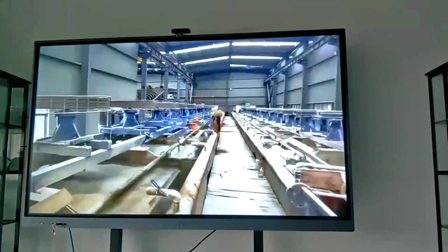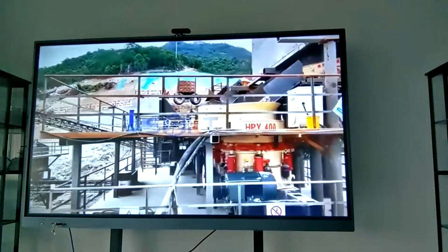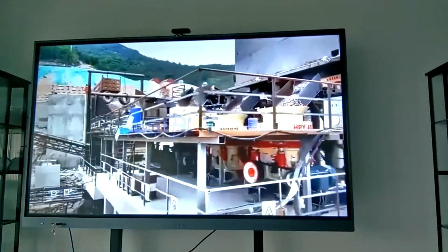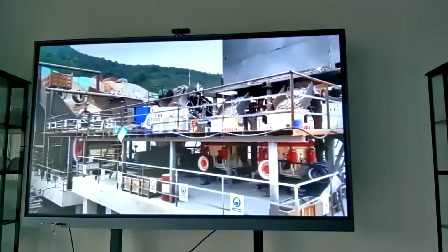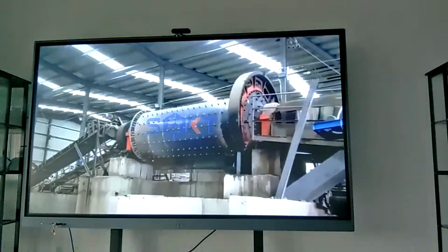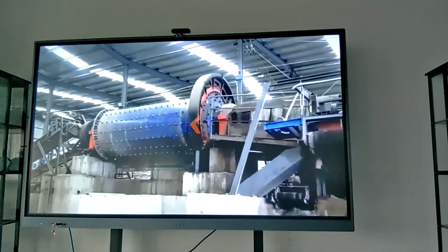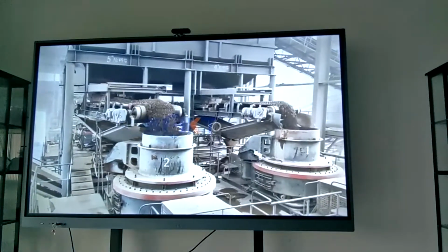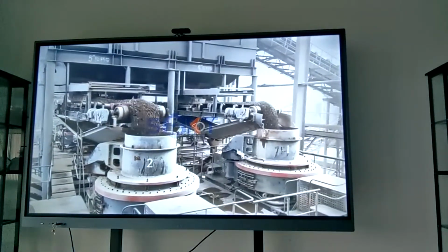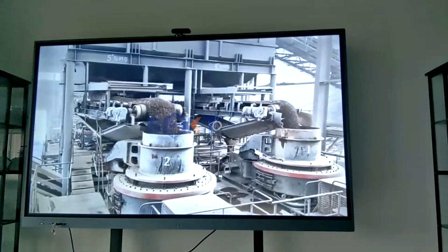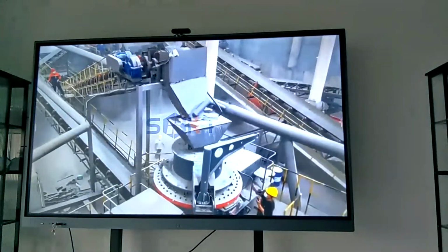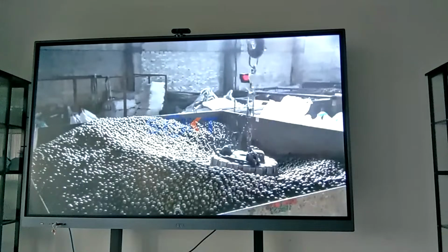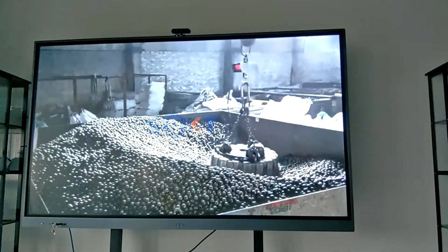Flotation is suitable for situations requiring comprehensive recovery or subsequent smelting. Pre-treatment has the highest cost, only suitable for high grade, usually concentrate grade more than 30 grams per ton, or difficult-to-process ores that must be treated.